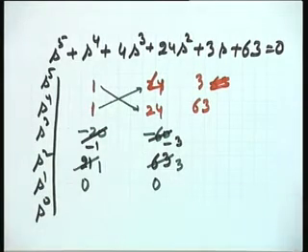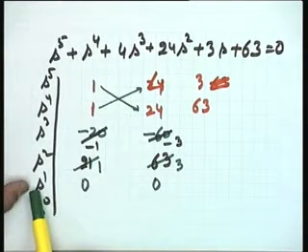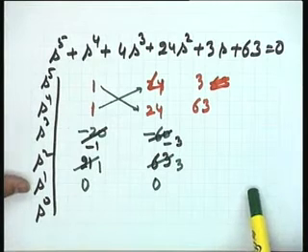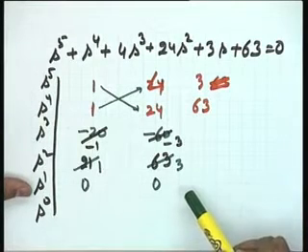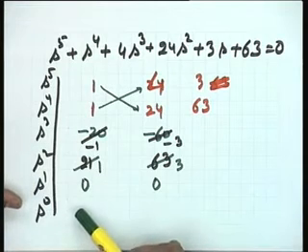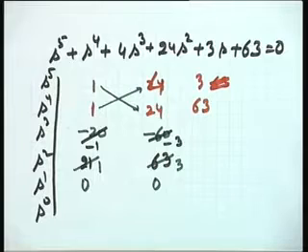His question was, when do we come across the situation when there could be poles on the j omega axis. Please see that in this particular case a complete row in the Routh array is a 0 row, and the problem is this, that you cannot continue with the array formulation. The coefficients of the next row become undefined, as has been rightly said.